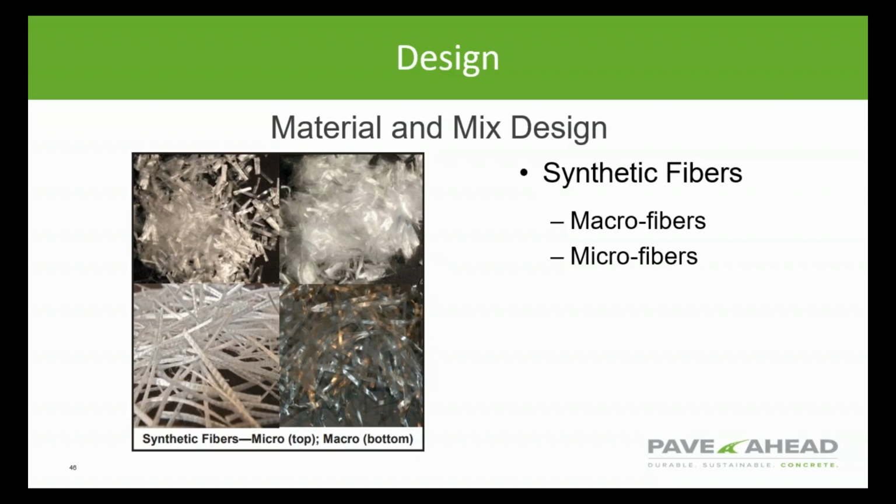Synthetic fibers engineered for use in concrete can withstand the long-term alkaline environments of concrete. These fibers are manufactured polymer-based materials such as polypropylene, nylon, or polyethylene. Synthetic fibers are added to concrete before or during the mixing operation. Synthetic fibers can be a benefit in both plastic and hardened states. And some of those benefits that we see are reduced plastic settlement cracks, reduced plastic shrinkage cracks, increased toughness and impact resistance, and providing energy absorption.